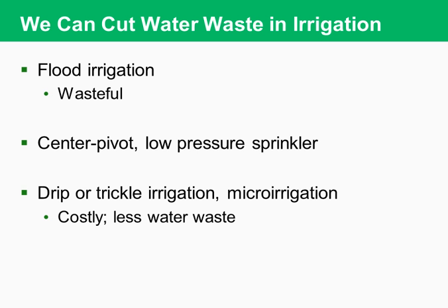But we're moving away from that, hoping to go toward more of a center pivot. It's kind of like a low pressure sprinkler system, and that one has pumps that spray water on the crop, and at least there you'll have about 80% of the water actually reach the crop in that situation. And if you use a low energy but precision application sprinkler, you'll get 90 to 95%.